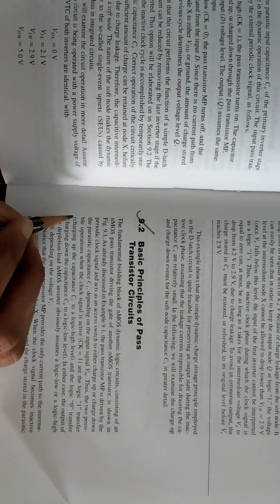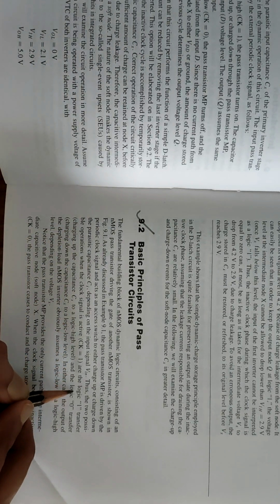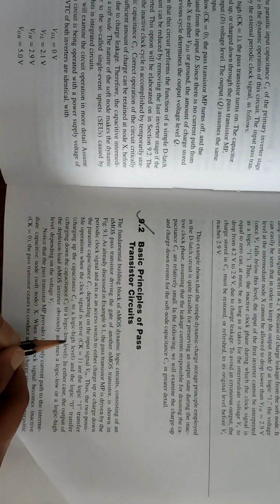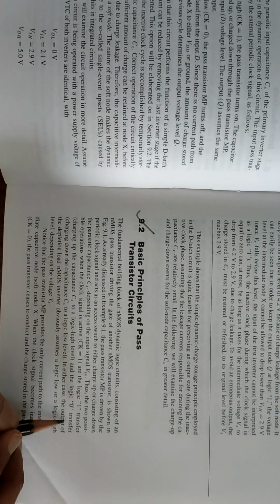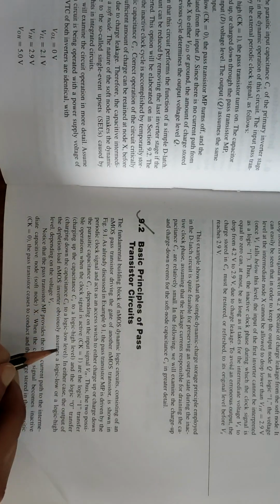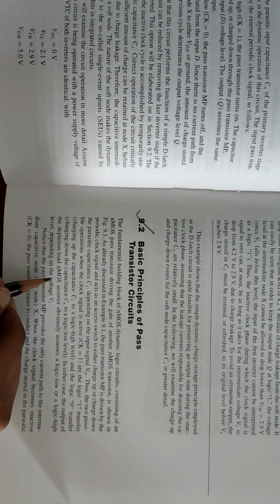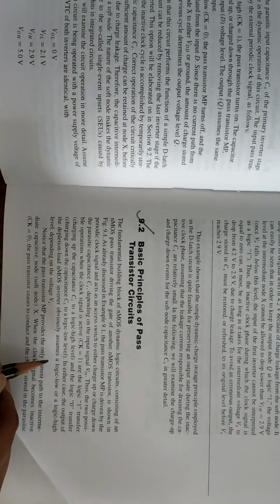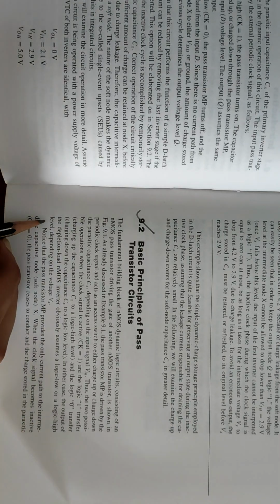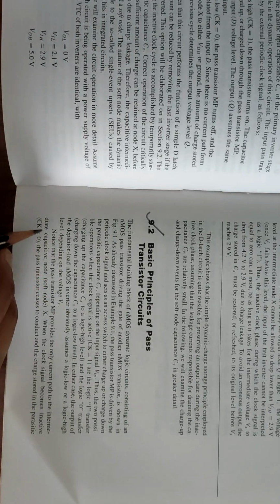Thus, the two possible operations when the clock signal is active, Ck equal to 1, are the logic 1 transfer, charging up the capacitance Cx to a logic high level, and the logic 0 transfer, charging down the capacitance Cx to a logic low level. In either case, the output of the depletion load NMOS inverter obviously assumes a logic low or logic high level depending on the voltage Vx.